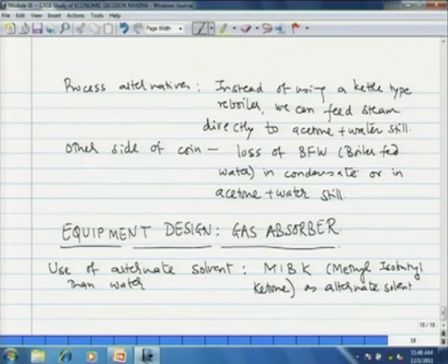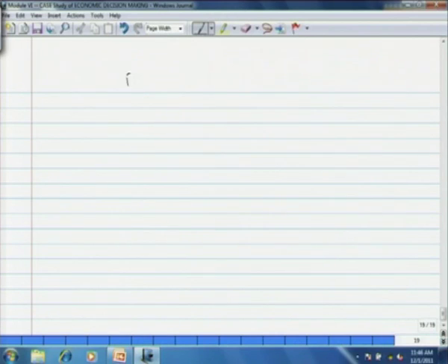Now, that loss again can be estimated from vapor liquid equilibrium, like the basic relation Pt y_s equal to gamma_s Pv_s into x_s, where s denotes solute, which is presently the acetone, and Pt is the total pressure of the system, Pv is the vapor pressure, gamma is the activity coefficient, x and y are mole fractions in liquid and gas respectively.